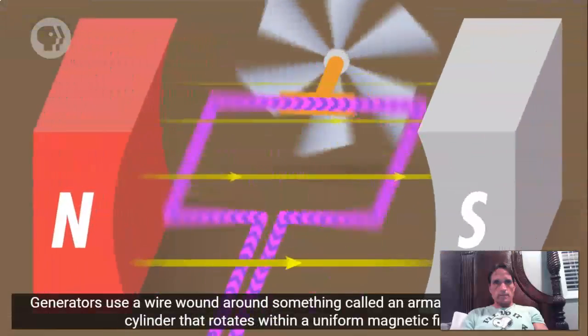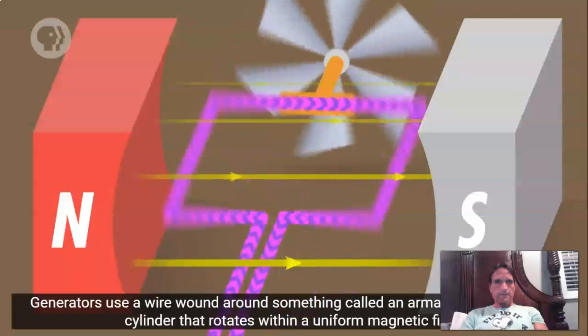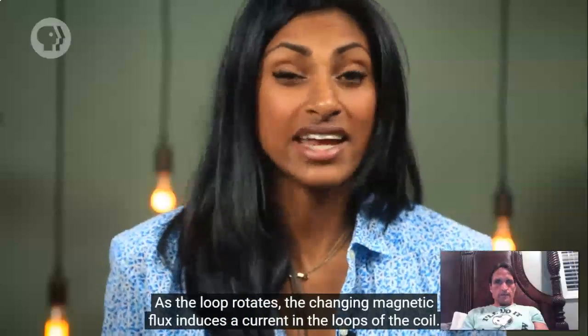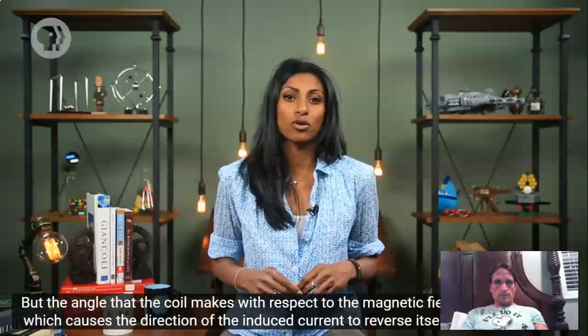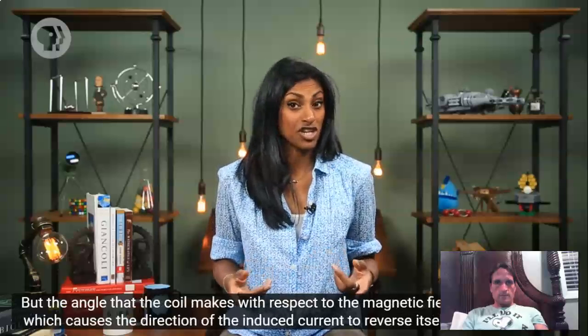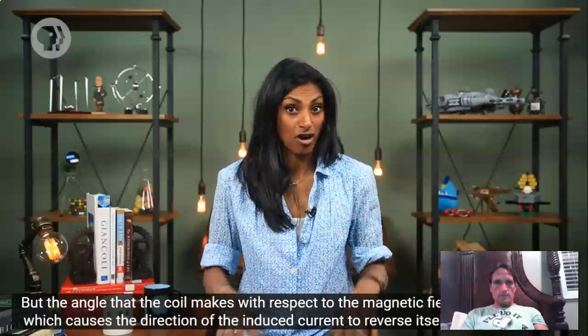Generators use a wire wound around something called an armature, basically a cylinder that rotates within a uniform magnetic field. As the loop rotates, the changing magnetic flux induces a current in the loops of the coil. But the angle that the coil makes with respect to the magnetic field keeps changing, which causes the direction of the induced current to reverse itself at every half turn.